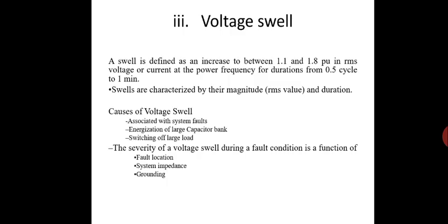If it is located nearby the load, then it is more severe. If the system impedance is very low, then also it is more severe. And if the grounding is not done properly, then also it is more severe.